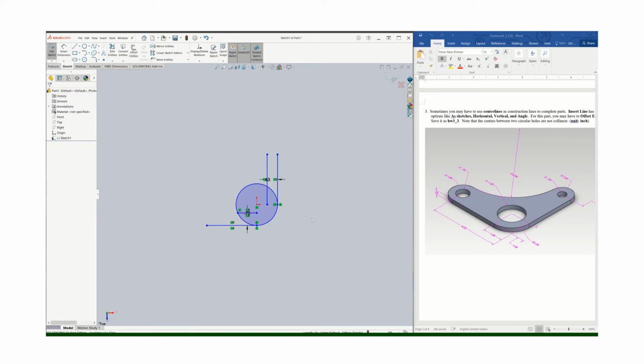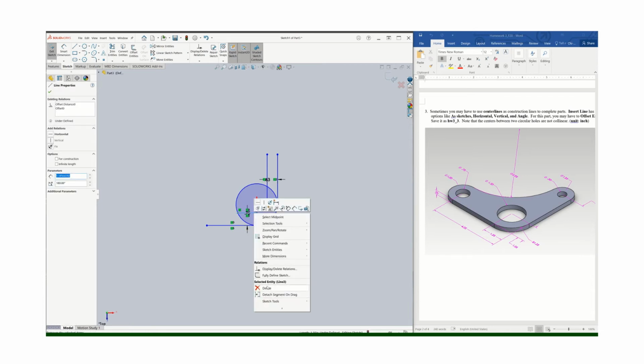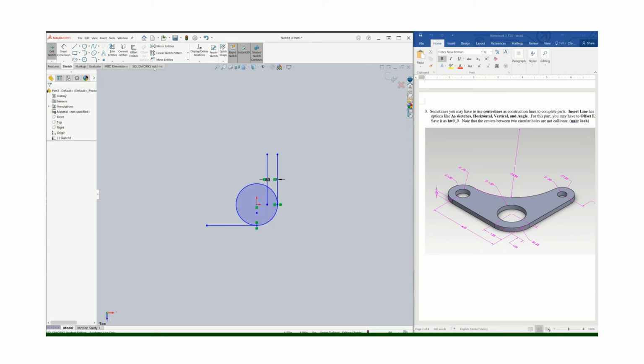And the second one is I have to draw a tangent line. Again, I already drew it, so I will have to delete this one. And I'm going to draw another offset of this line, this time up, but the distance will be 1.5 over 2, that should be 0.75. By doing those, I have created the horizontal line of 3 inches and the vertical line of 3 inches.